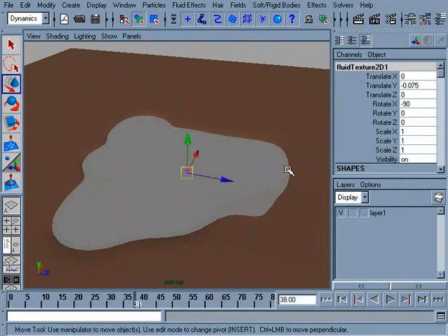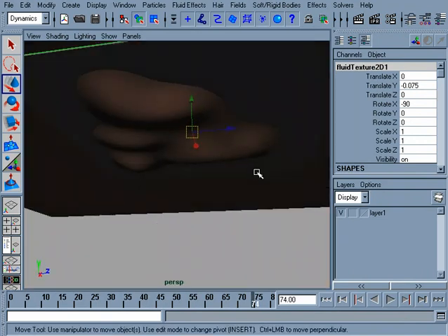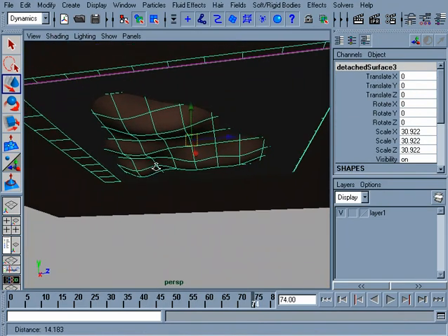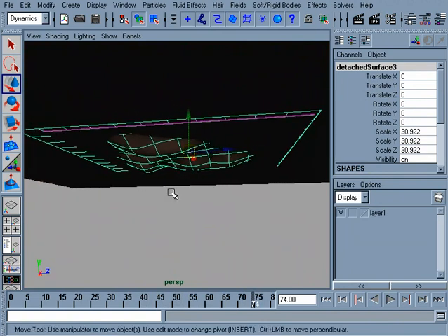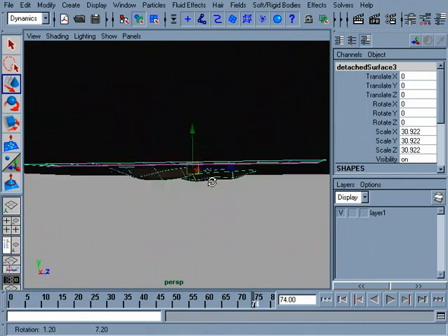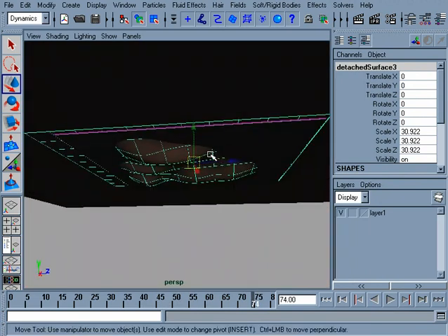There's sort of an area of no influence, I guess you could call it, that if a particle lands right on this boundary in just the right place, it's not going to know what to do, and so it gets stuck, like you can see with some of these. So the easiest way that I found to fix that is let's take this NURBS surface and duplicate this, so that we actually have two of these NURBS surfaces.